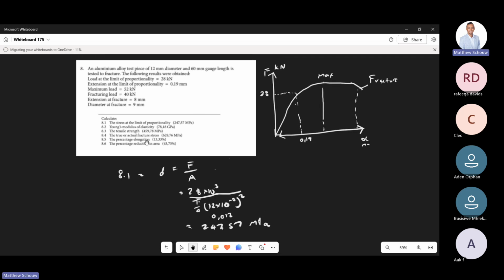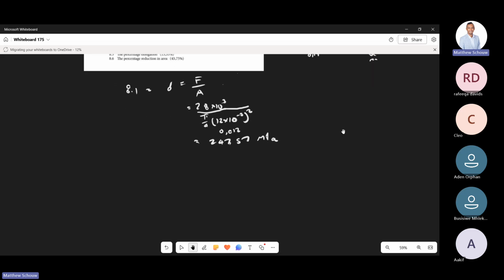So now the next part, right? It's asking for the Young's modulus. There's a lot I can talk about there. Just remind me to talk about it afterwards. I'll just mention right now that all materials have a different elastic modulus value. For steel, you could get anything from 190 to 210 gigapascals. For aluminum, you can get anything around 60 to 67.5 gigapascals. And I can't remember what the other one was now for copper. Anyway, they all have different values, and I can show you the table if you want. But the relationship